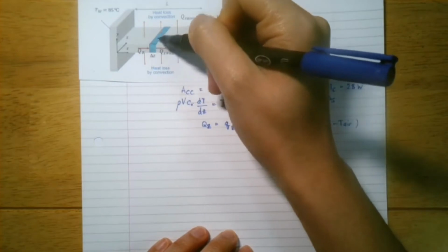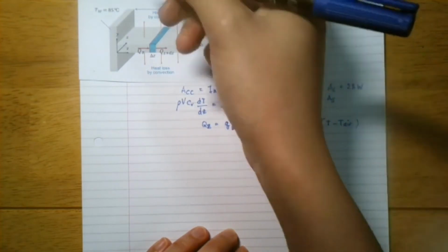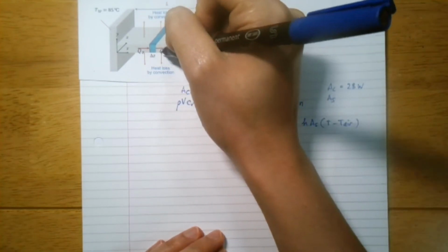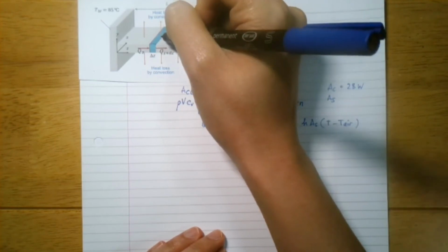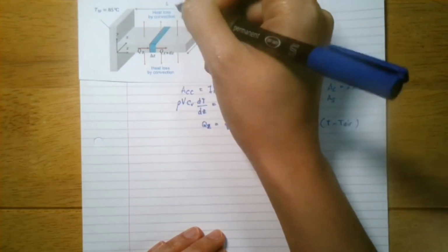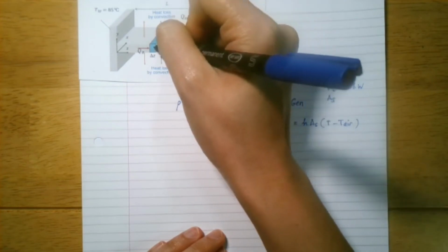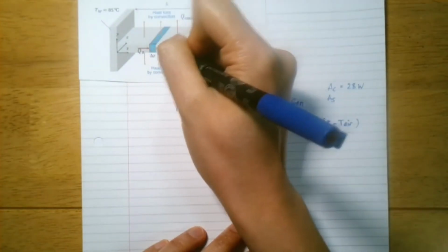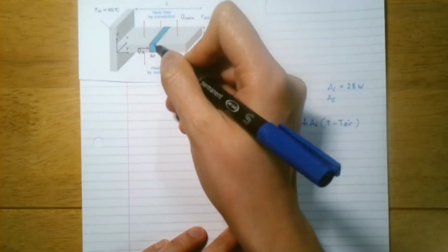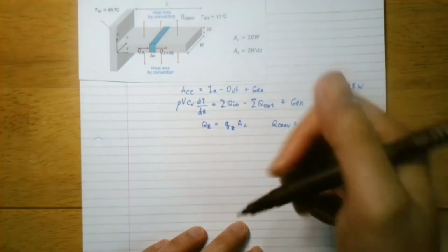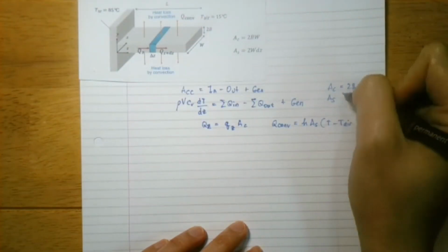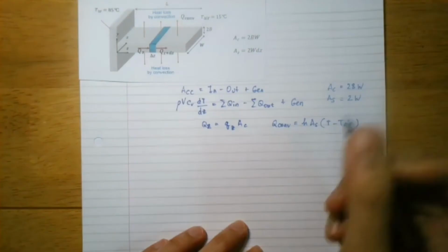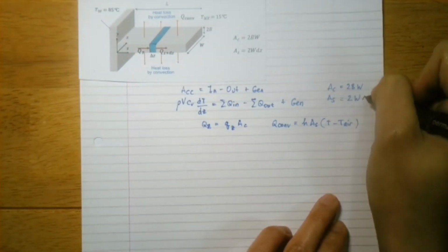So this is our control volume. Okay, and when we talk about convection, the area perpendicular to the heat flow due to convection is this. Okay, so that is the width W times delta Z. Okay, but we have two because we have one at the bottom of this. So we have two surfaces, one at the top and one at the bottom. So we have 2 times W times the thickness of our control volume, delta Z.